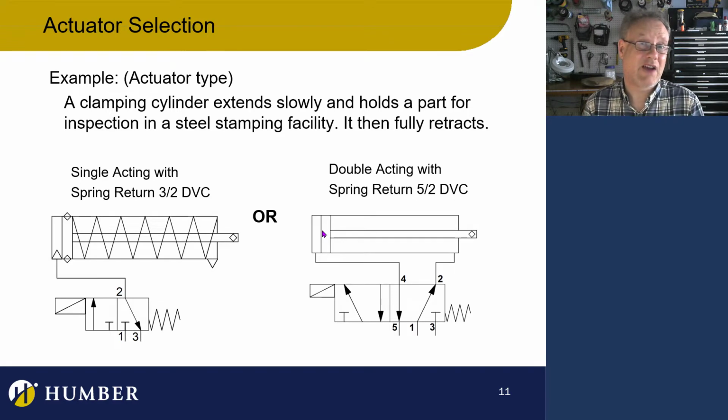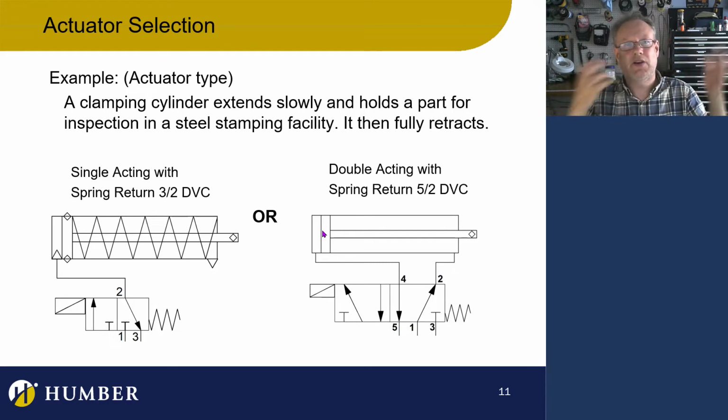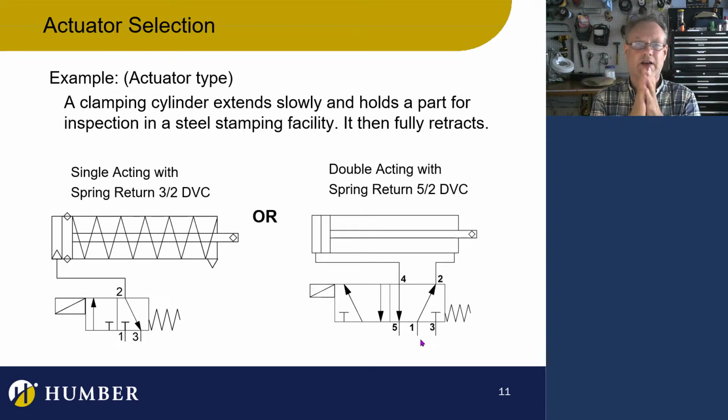And actually, you know what? The air is probably going to, even just in the lines, in the hoses, in the pipes, there's enough pressurized air in there to run this cylinder enough to get it out of the way so it's not pushing anymore. You don't even need one of those accumulators. If the spring takes over, it'll send whatever pressurized air is left in the lines, just a little bit. Plus, there's a whole tank on the compressor, right?